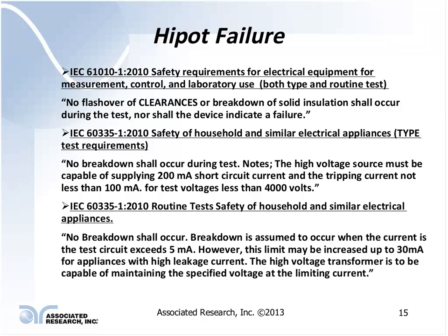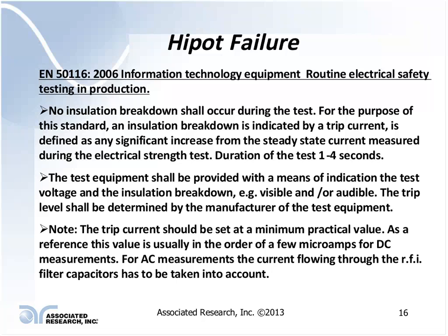When you set up your workstations, make sure that the workstations are guarded so you are protecting your operator from any potential electrical shock hazard. Doing Hipot testing or safety testing should not be hazardous to the operator. Keep that in mind. I can't stress that enough.